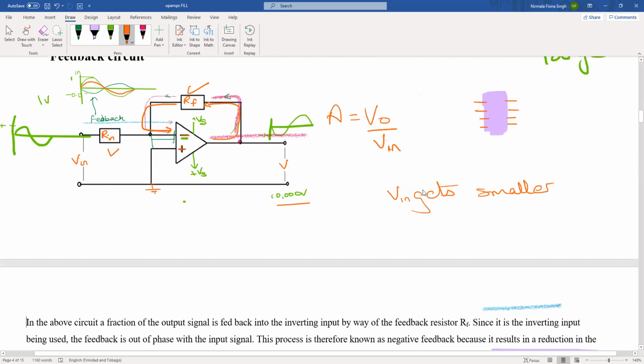So instead of having to replace our very complex looking operational amplifier that has 8 pins that you need to attach into your board, and something here is going to get soldered, all we have to do is connect it to one resistor and then connect it to another resistor coming out. So our gain, which is what we need in an amplifier, is meant to increase your signal, is simply going to depend on these two little resistors.